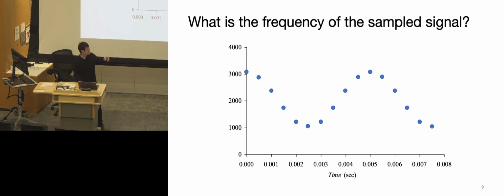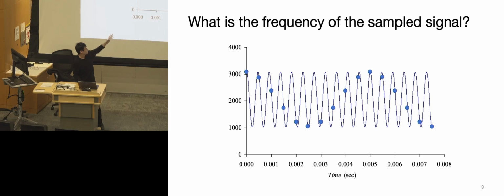And if we go back a little bit to here, if we have something faster than 1K in the original signal, or in this case, much faster, then using the same sampling rate, it will essentially have the same sample point distribution as the previous 200 hertz. So this just gives you an idea of what aliasing means. It means if you have higher frequencies.